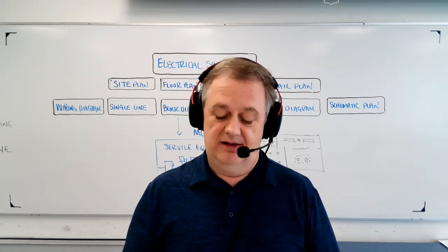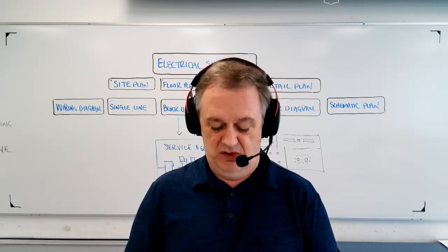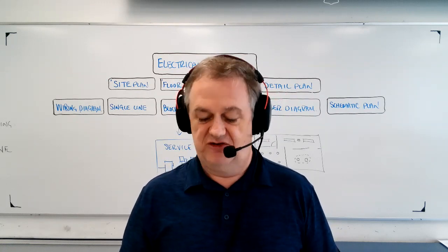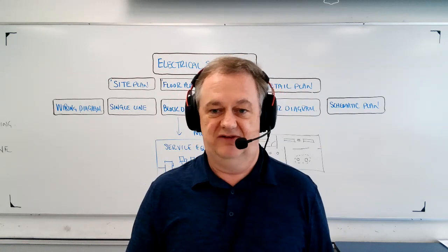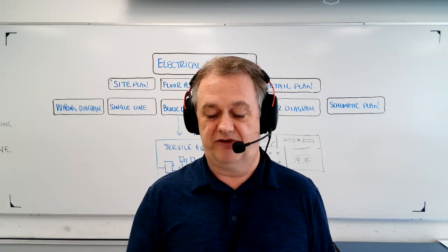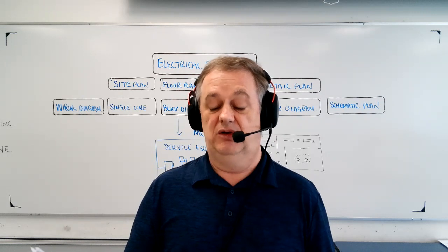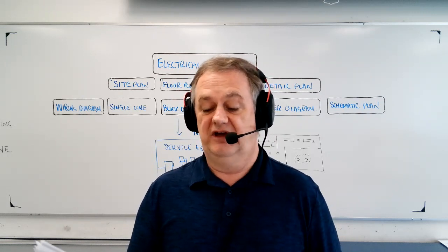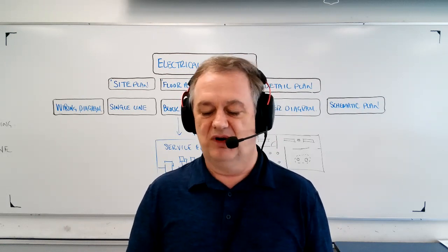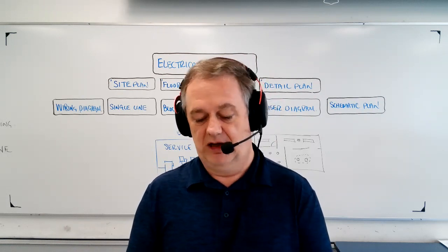Page 29. Now if you look at it, it's kind of like an elevation because you do see the side view, but here's the difference. This drawing would be classified as a section primarily, because you're seeing a cutaway of what's going on underground, the concrete ballast below the EV chargers, and it shows how the conduits enter and stuff like that. So even though you may think, oh, it's kind of like an elevation because I can see the brick facing on the building, really it's primarily a section, okay?